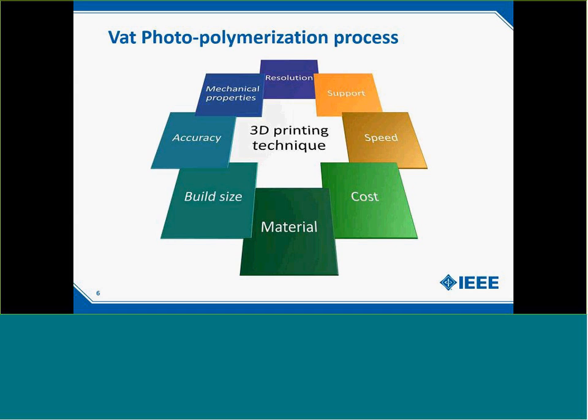So what I'm suggesting here is that when we're using this vat photopolymerization process, we consider the end-to-end process. We need to consider as well that the SLA can be used as one step in the whole manufacturing process. It doesn't need to be used only for the final part. We can print, for example, a mandrel. The mandrel is plated for the electrical conductivity and for the mechanical properties. The mandrel can be removed. So SLA, for example, can be enabling for RF components just as a printer of a part that will be